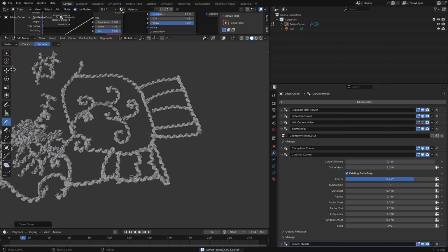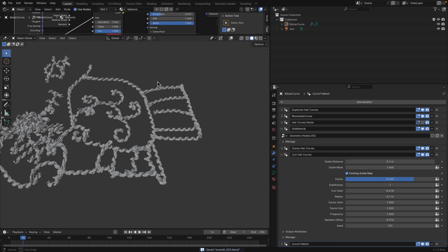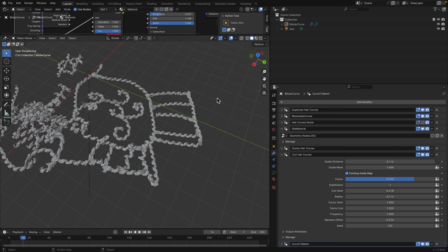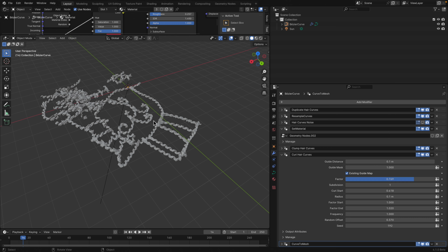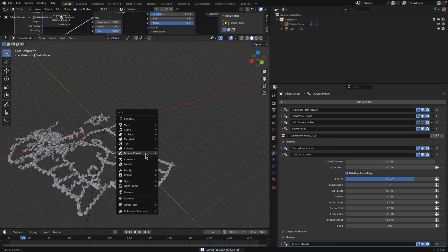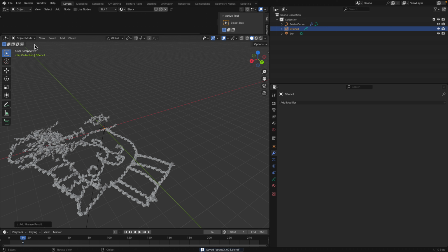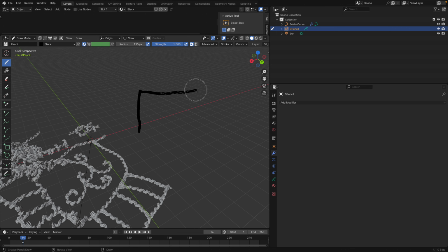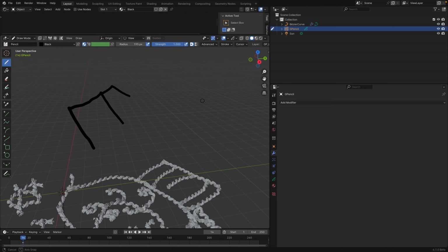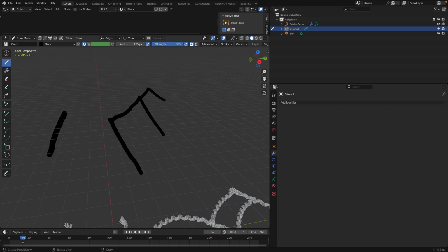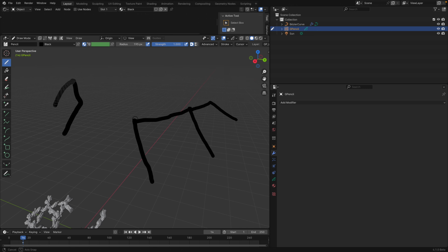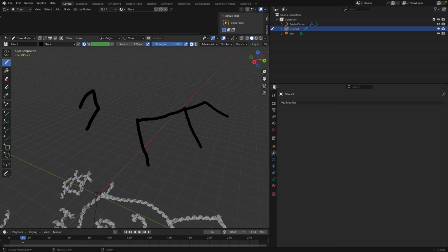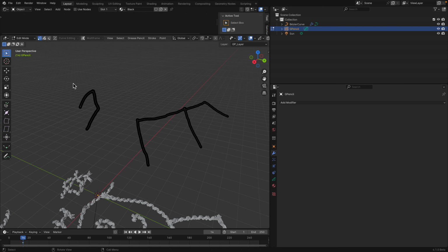I mentioned that grease pencil can be used together with this guy over here because it's currently a curve, right? If you use grease pencil blank and then go to draw, increase radius. I like using grease pencil first because you have a lot more freedom and you can connect the dots. If you have two strokes like this floating in space, you can go to edit mode, of course, hit Tab, select grease, and you can move it.